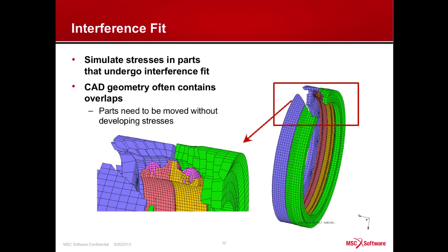There's some overlap. As I said, in some cases that is intentional. So that is the second reason: the overlap itself could exist prior to installation. For example, a seal could be created with its original geometry, and with FEA, you may need to figure out the stresses after the installation of the seal, after you stretch it and place it in position.